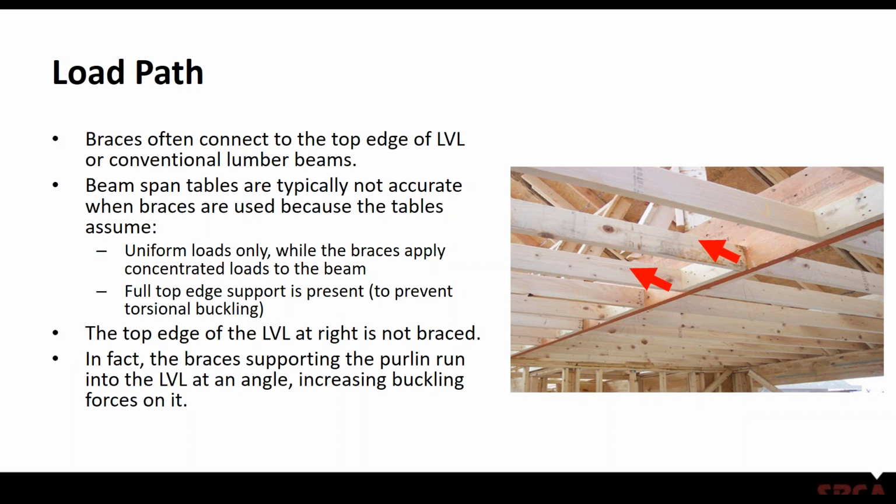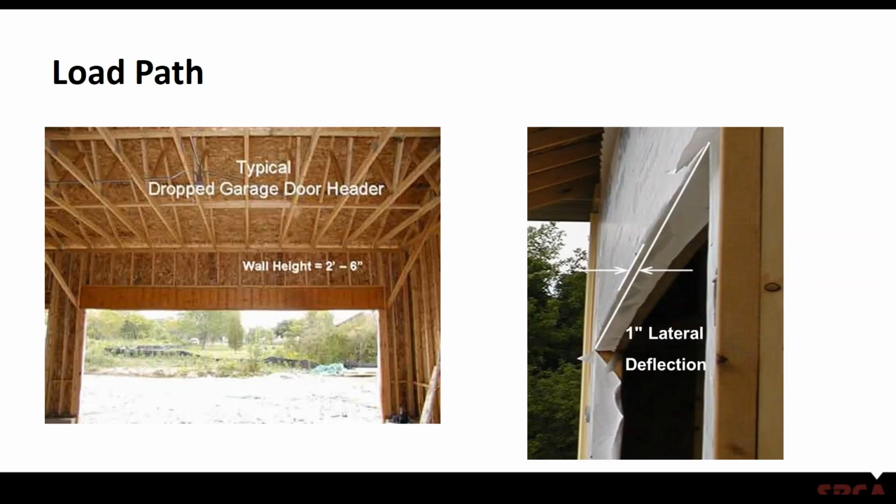And another area where you can see these problems can occur would be load-bearing garage door headers. In this case, it's a fairly large LVL beam, fairly highly loaded, and even before the project finished, that little cripple wall that sits between the bearing location of the roof trusses and then comes down and sits on top of the beam, you really have a hinge point between the bottom plate of that wall and the top edge of that beam.